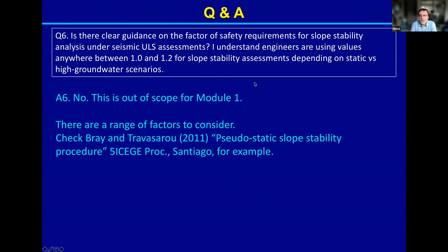Well, if you're doing equivalent static analysis, obviously you are severely misrepresenting or approximating the load that we are using in the assessment. Second, this factor of safety cannot be taken outside of the context of the strength of soil and what the consequences of potential loss of stability are. In that sense, having a factor of safety of 1 for different strength characteristics of the soil will imply completely different responses, and one could be acceptable performance, the other could be entirely unacceptable